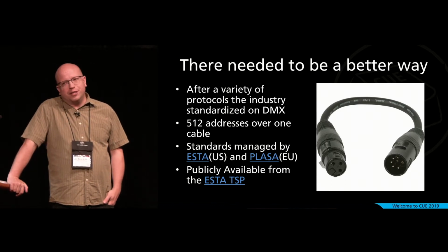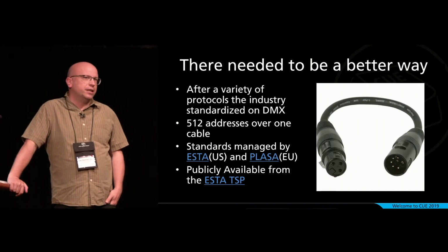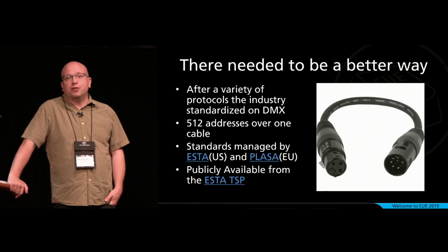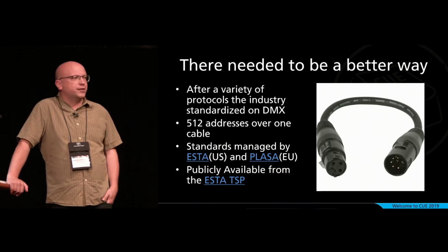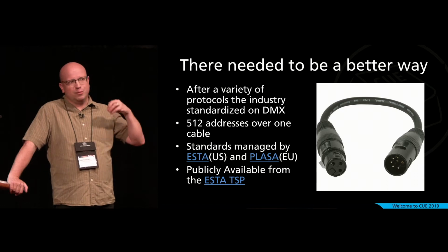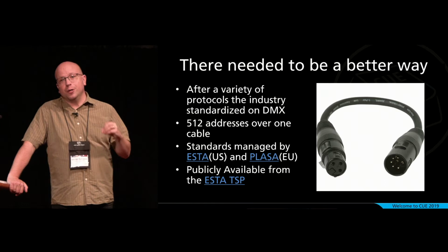So a variety of things were tried, again, by different companies. They were generally proprietary. And then we ended up with DMX. So DMX512, it's called DMX512 because you control 512 addresses, 512 dimmers at the start, over one piece of cable. Great, so we've gone from these big fragile cables with lots and lots of connections to one cable with a standard way of doing things.